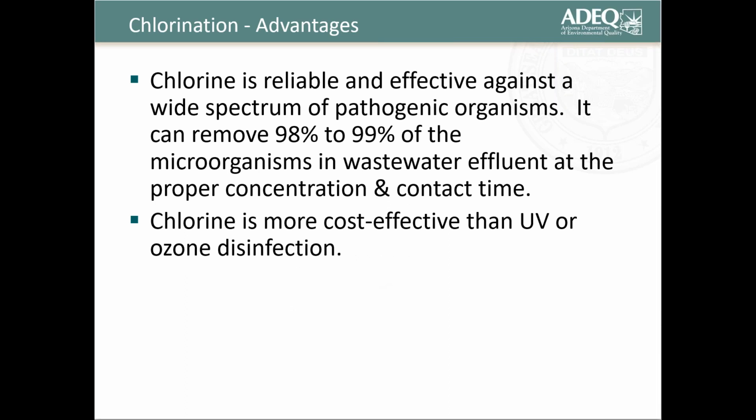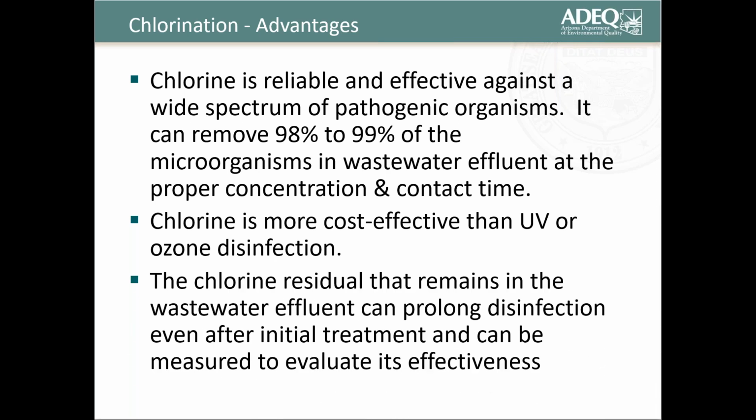Chlorine is more cost effective than UV or ultraviolet light disinfection or ozone disinfection. The chlorine residual that remains in the wastewater effluent can prolong disinfection even after initial treatment and can be measured to evaluate its effectiveness.